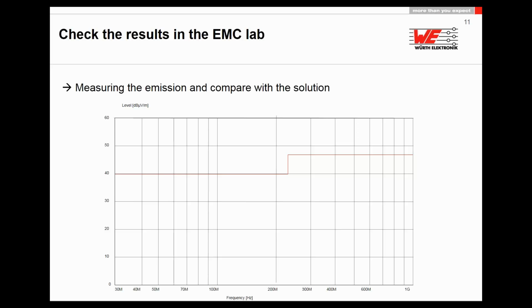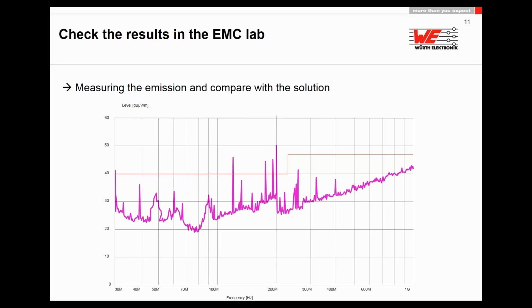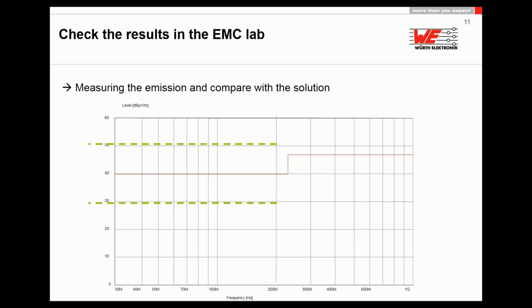So now we go back to the application. Remember the EMC measurement: you have this level of the EMC requirement, radiated emission, you make your first shot, you know you are failing, then you go home, you want to cut this 20 dB from somewhere, you find out this is on the VCC cable, and then you calculate the right ferrite inductance. You put it in and you go back to the EMC laboratory with your redesign, and you wish you will pass the EMC test.